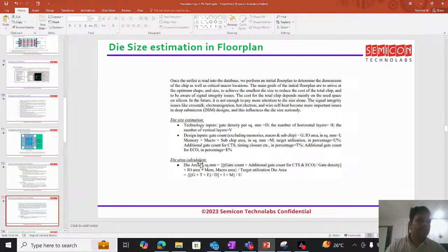But make sure that you are not leaving too much extra space in the design, because it will be problematic, not just in wasting the die area, but also in closing the timing, because the cells will be spread across. So come up with a reasonable optimized die area which is suitable for your program and your block.